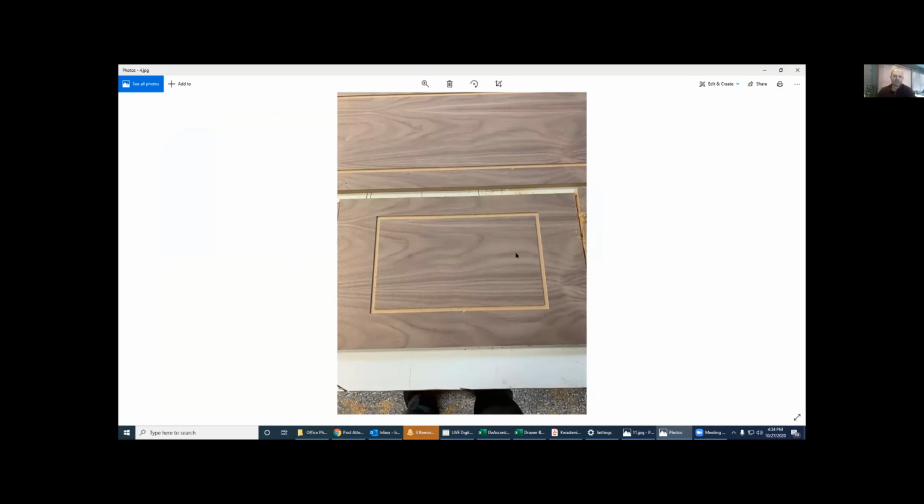So I ordered this 1/4-inch material without a balanced backer. So it had walnut veneer on the face and raw MDF on the back. And it curled before I could get it flat on the CNC, and my vacuum wouldn't hold it down. So I had to lay every one of these out, know the panel that I was routing flat, and screw a fixture down to it to hold it flat instead of letting my vacuum do the work.